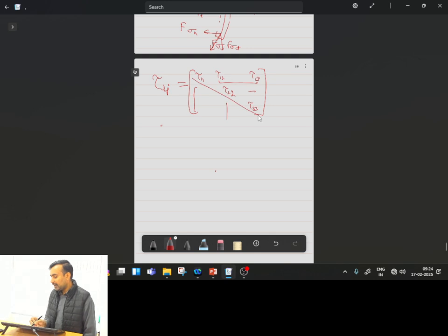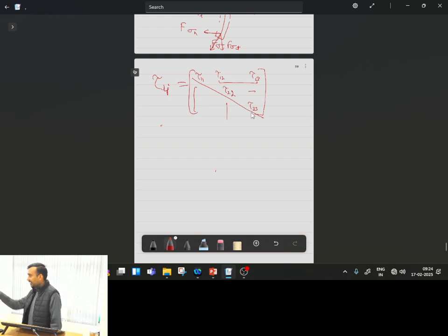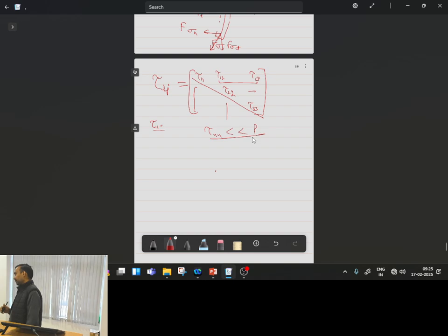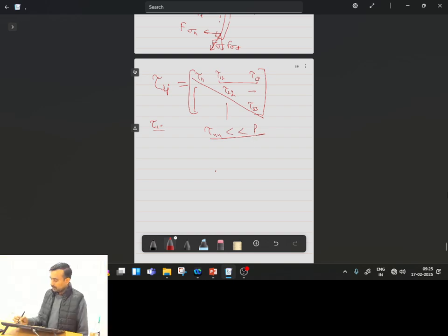But for the components here, the force acting on a plane is in the same direction as that of the plane's normal, so that is nothing but a normal force. So we do have some contribution of normal forces because of the viscous effect. But typically the normal deviatoric stress caused by viscosity has very small magnitude in comparison to the pressure. That's why the majority of the time we neglect this contribution. Is this point clear? Are all clear with this idea?